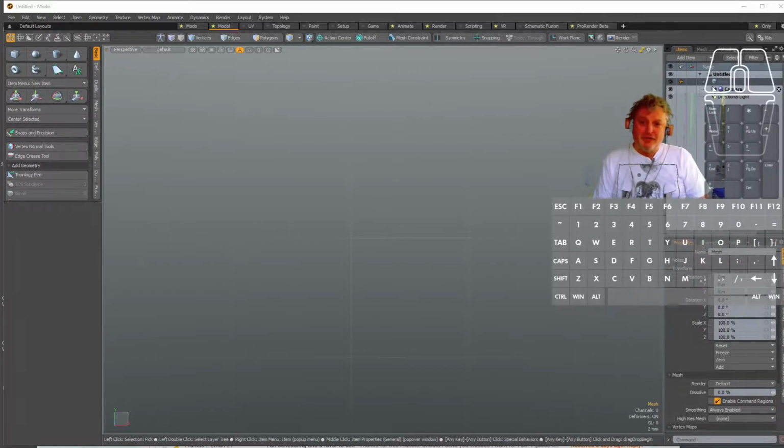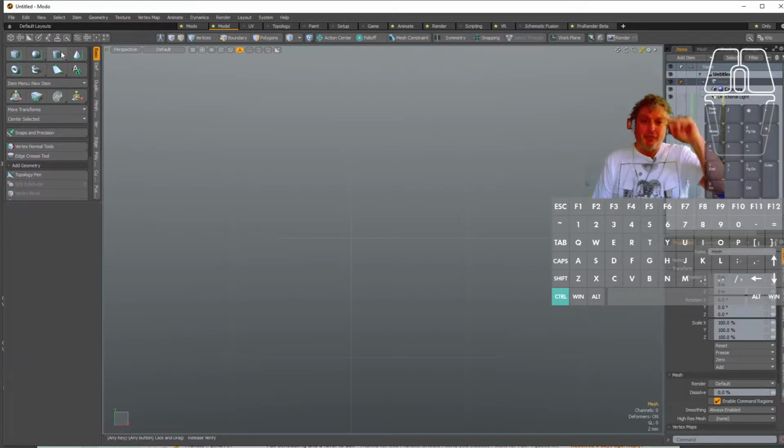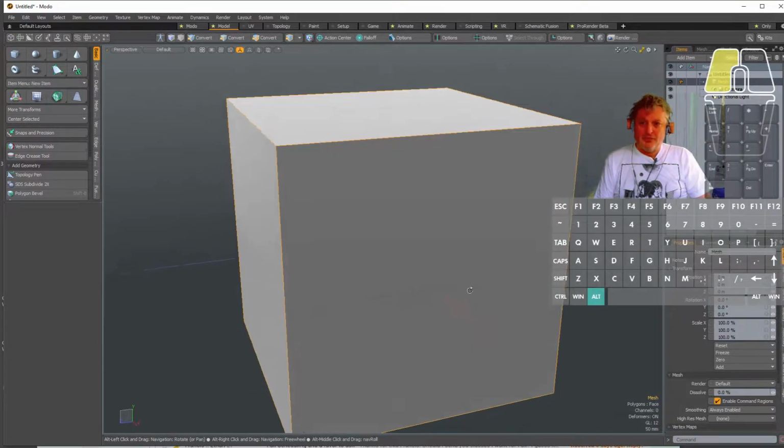I'm in one mesh here. There's nothing in it yet. I'm going to put in what's called a unit solid, which is this cube. If I hold down my control key, see how that turns into the thing with the green ruler to the left and right of it? What that means is if I click it, it will give me a 1 meter by 1 meter by 1 meter thing. So if I clicked it and I hit Shift and A, that should be that.